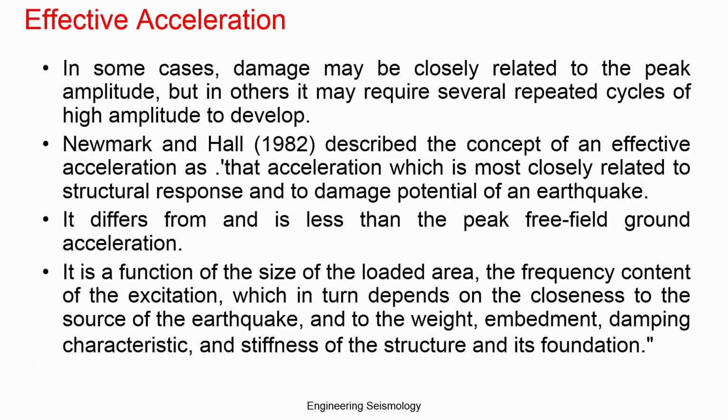It is a function of the size of the loaded area, the frequency content of the excitation, which in turn depends upon the closeness to the source of the earthquake, and of the weight, embedment, damping characteristics and stiffness of the structure and its foundation. So, this is a composite mix of structural parameters and acceleration. Many repeated cycles of acceleration can cause damage, so such repeated acceleration has been defined as the effective acceleration.